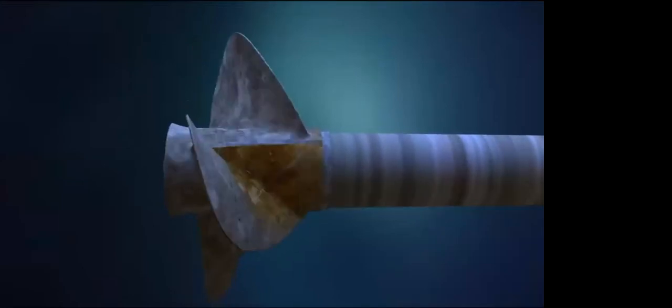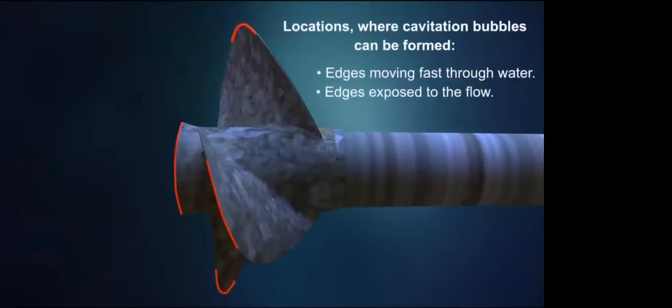But how is it possible that the pressure becomes very low in certain areas of a fluid? Let's have a look at an example for illustration. If objects, such as blades of a ship propeller, are moved through water, there is a higher pressure on the side facing the flow and a lower pressure on the opposite side. On other edges exposed to the flow, low pressure can also lead to cavitation.